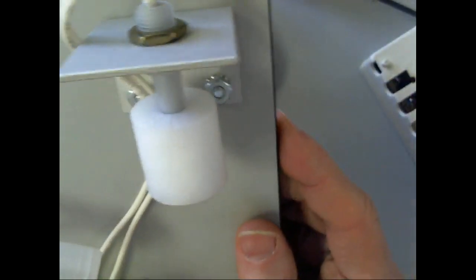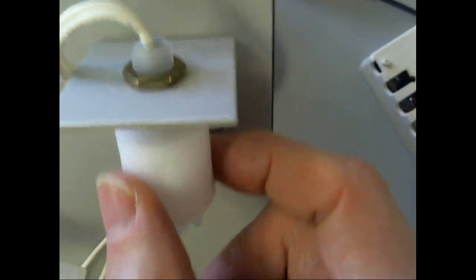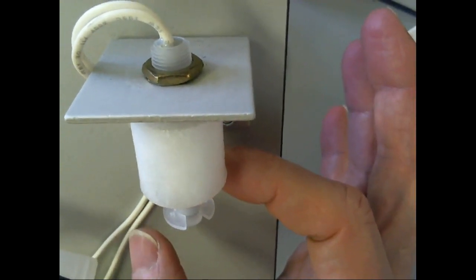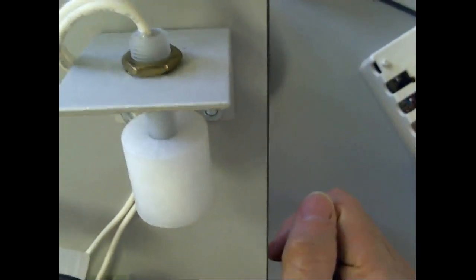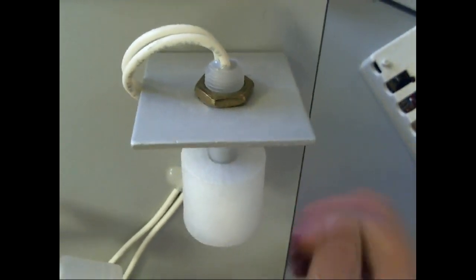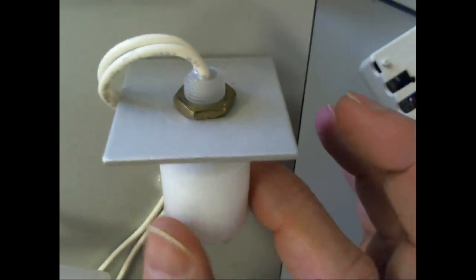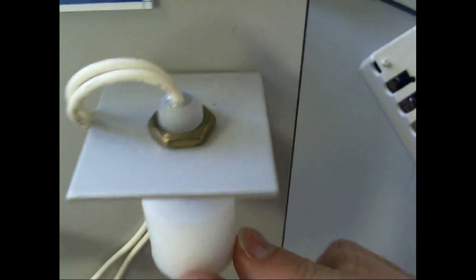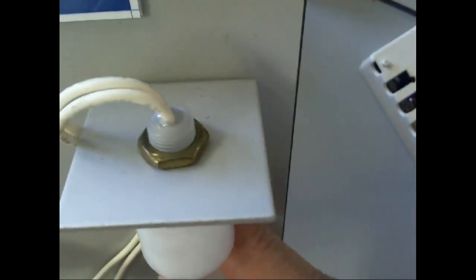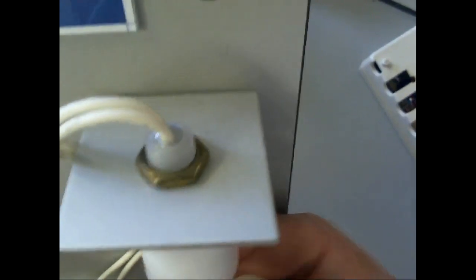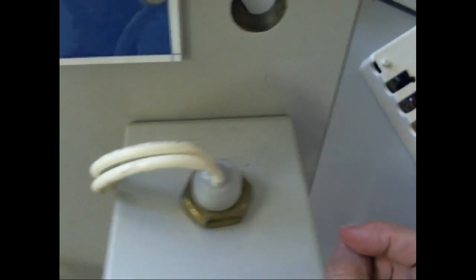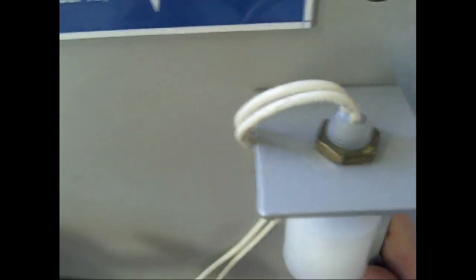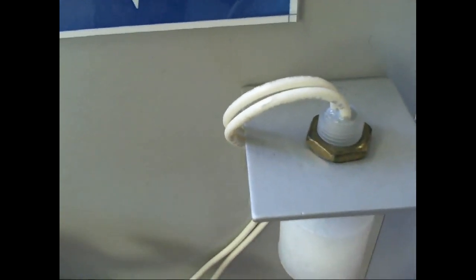Now this one, here's the float right here. As the material or liquid builds up, this would cause it to rise up and close the switch. And then this right here would cause it to open. Now this one, you change it from normally open to normally closed, and we're not going to explain why, by snapping this off and reversing the float. If you reverse the float, one way would be normally open. You snap this off and turn the float around, it turns it into normally closed. And like I said, in sensors, we would explain how that works. We don't really need to know that. All we know is float switches are either going to be normally closed or normally open.